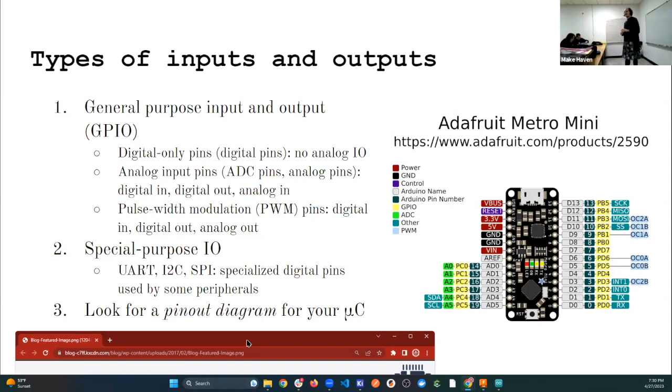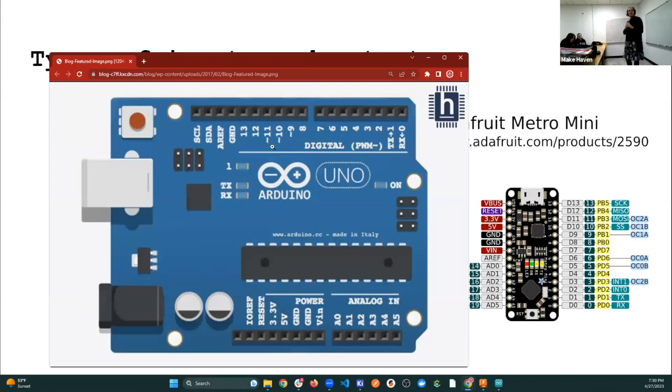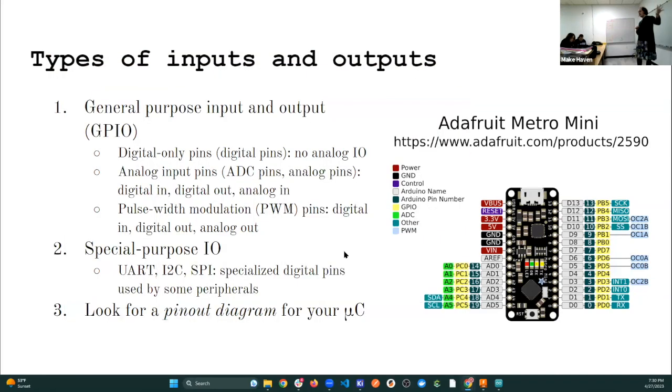Yes, do that. If you make the first steps off the path, you may do that with an Arduino Uno. It has labels: these are the PWM pins, marked with the little tilde, and over here, these are the analog in. These are all digital. The silk screen can often be very helpful. The boards are often marked in order to help you do that. This is one of the advantages of a bigger board, like the one that Corey just showed, compared to the tiny board that you have. There is no room for such detailed labels on the tiny boards. So for those, usually you have to go to whatever instructions came with the board.